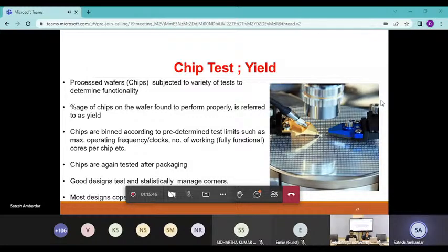it is not just theory, you have to soil your hands. You have to run several lots to fine tune the process, identify the defects, and over the years you get mastery over this. Also important is that in the design of the chips, we should incorporate the corners, and know how to manage the corners. Basically, managing corners refers to the extremes in the process variation. So the design should be able to cater to the variations in the processes that are generally encountered, because we are talking in nanometer levels, in angstrom thicknesses. So there is bound to be some variation.